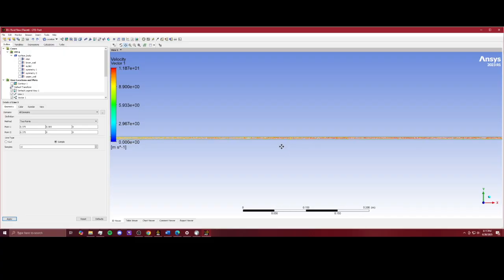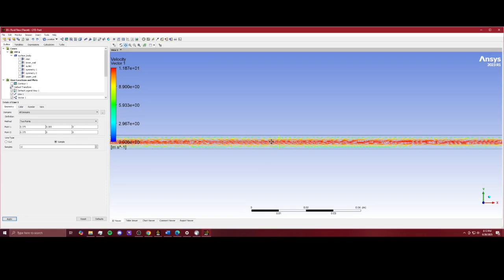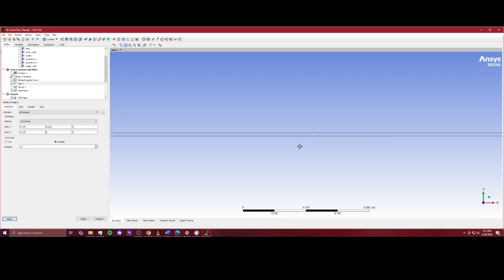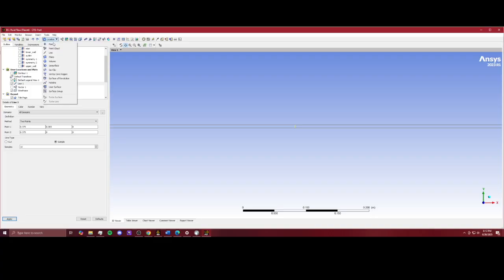Oh, yeah. Right here we can see our midline. We could turn off this vector so we can see it better, right in the middle of our pipe. And then we can also make an end line. Like over here, since our pipe was 750 millimeters long, this is what I saw in the tutorials when I watched them, just make sure it's a little bit smaller than the length of your pipe. So 0.749 meters, 749, yeah.